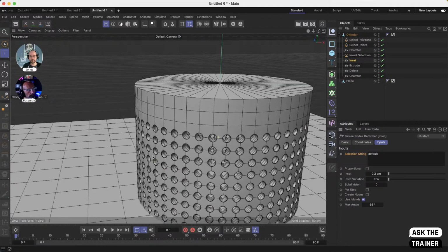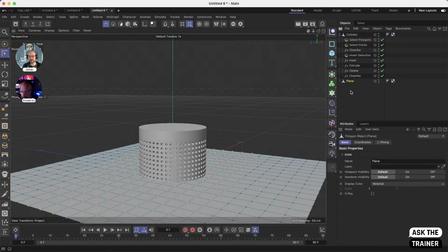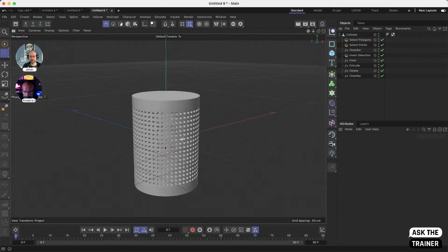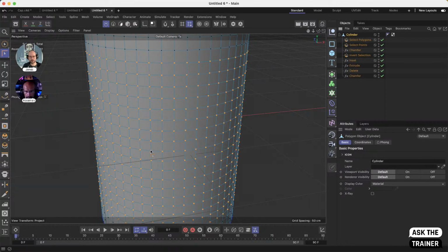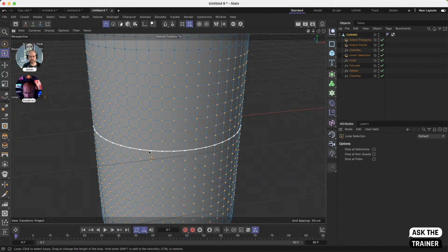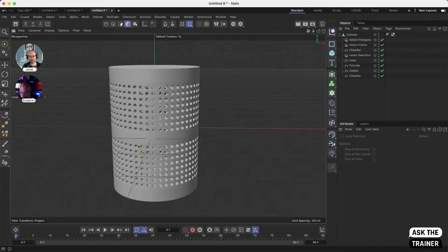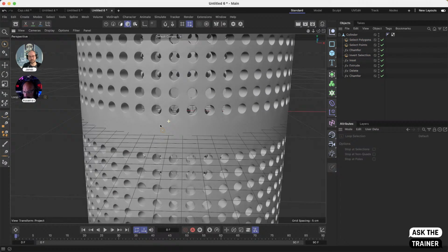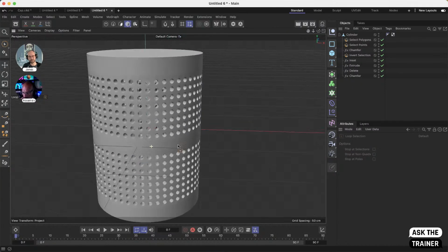Right, and now we created this. And it's still very procedural, except for the initial geometry, it's completely procedural. So now we can also remove parts of this point selection. So let me go to loop selection and just delete these two to create 2 lines that don't have points, like so. All right, so it's all procedural. Now we are getting these artifacts, but when we go small enough, you won't see them.